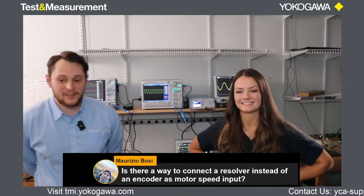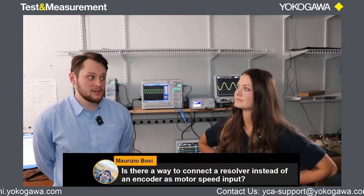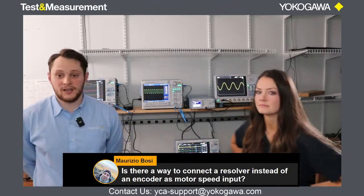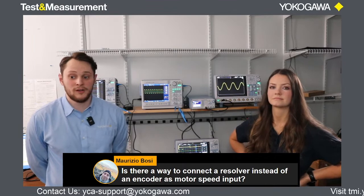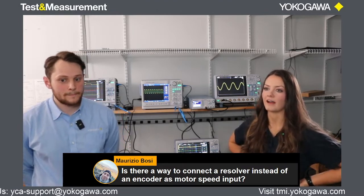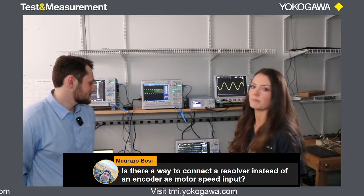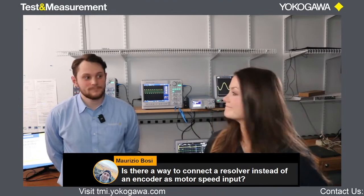In the WT5000 itself, the inputs that we allow are an ABZ encoder or just a speed device, but not a resolver. We take resolver inputs into our ScopeCorder. It has a specific resolver math calculation, but the WT5000 does not have a resolver analyzing component. So if you needed both of those components, like the accurate voltage, current, and power, and then the resolver input, you could combine these in the IS8000 software and look at that all at the same time.